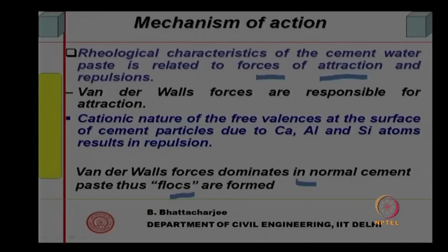Now, the repulsion in the beginning is less compared to the van der Waals forces. So, van der Waals forces dominate in normal cement paste, thus flocks are formed. In the beginning, if you do not add any plasticizer, cement tends to flock together because of this force, as it occurs in many other fine particles.